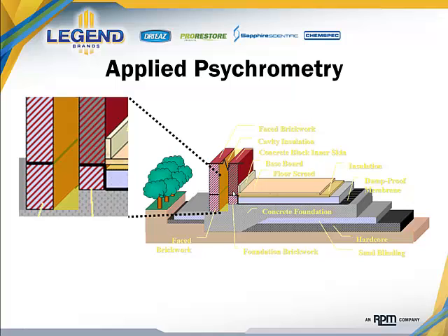If we do not get airflow into this space, then the drying rate on this lower area of the brick can be substantially impeded. How much airflow is needed here can be evaluated again in much the same way that we evaluated the flooring surface. The trick is to get a hygrometer into the space. I'll show you a couple of methods of measurement for doing this here in just a moment, but measuring the humidity in this cavity and verifying that that humidity is the same as the humidity wherever your drying resources are, your dehumidification, will verify that you have enough air movement.